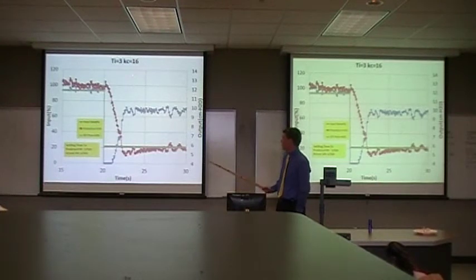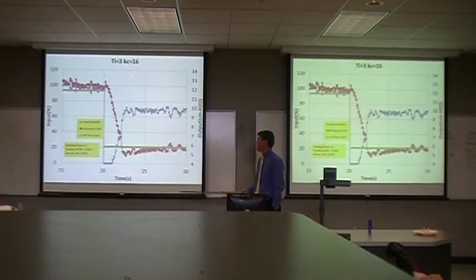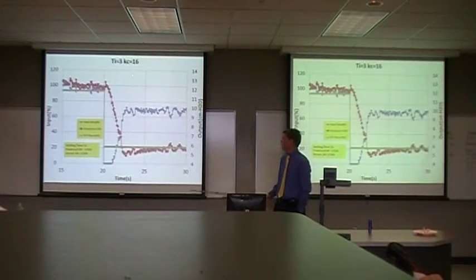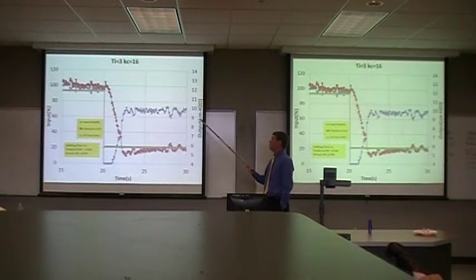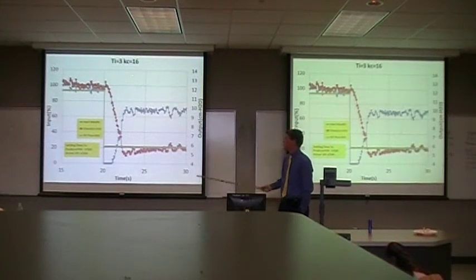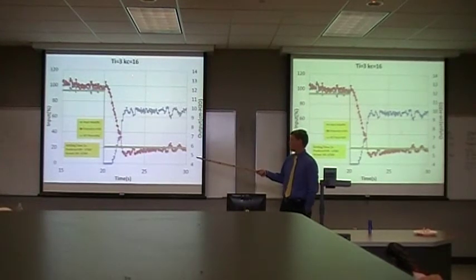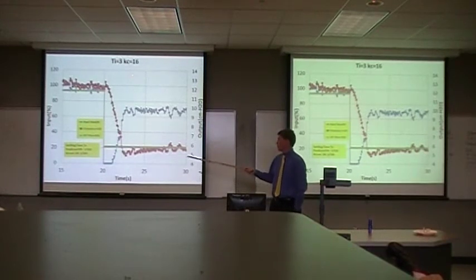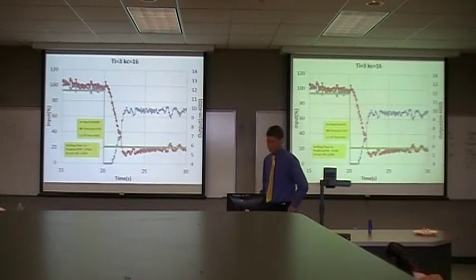This is an example of Troy's experiments. We tried the different tau I's and Kc's that were found in the root locus. For tau I equals 3 and Kc equals 16, whenever the set point changes, we found a settling time of 5 seconds. The predicted decay ratio was 1/500, and Troy said the actual decay ratio was 1/500.